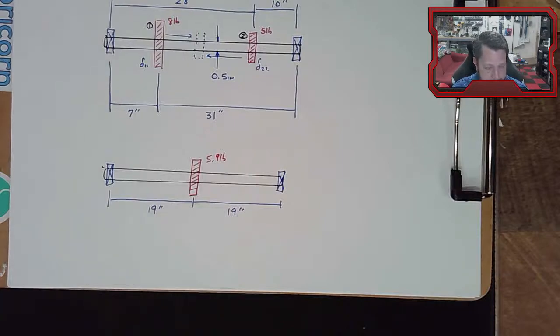So we take omega overall, the combination of the shaft's critical speed and the elements all translated to the center, equals 1 over the square root of 1 over omega elements squared, plus 1 over the shaft critical speed squared.